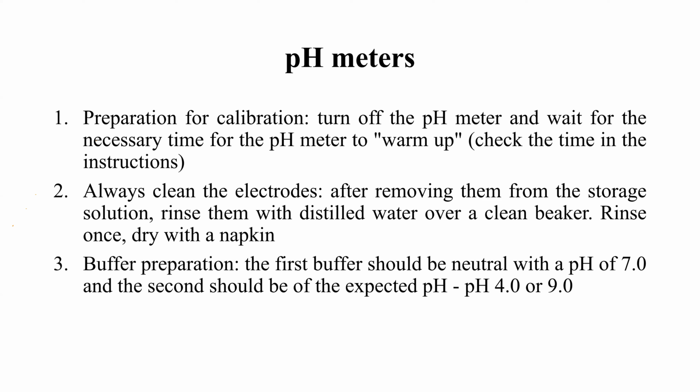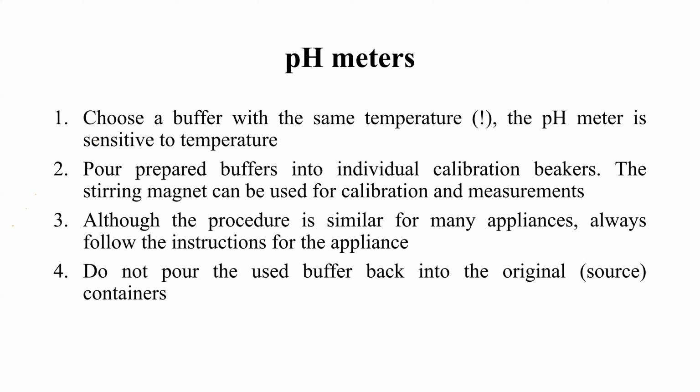Second, we move to acidity pH 4 or alkalinity pH 9. All buffers should be at the same temperature because temperature changes pH. Always calibrate before using pH meters.